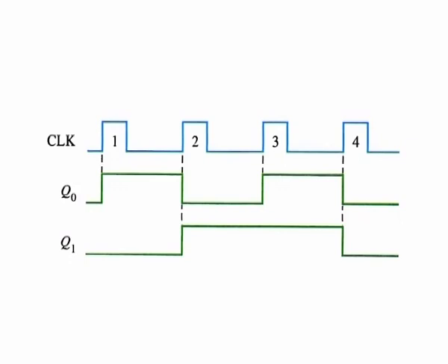Major waveform relationships resulting from the normal operation of a circuit can be conveyed completely without showing small delay and timing differences. However, in high-speed digital circuits, these small delays are an important consideration in design and troubleshooting.